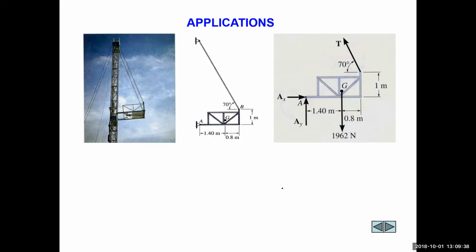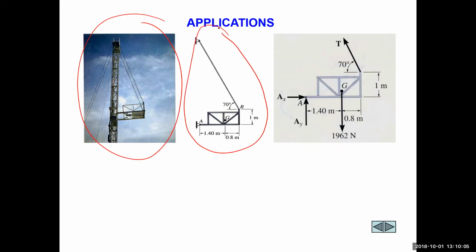So we're always going to look at just the external forces. So here's an application: a platform suspended from a tower. We might want to know what are the forces acting at the joints and in the cables. And typically what happens in real life, you're dealing with some real structure, and we then go through and idealize it. So we maybe look at it just in 2 dimensions if there's a lot of symmetry there. There's nothing different in the 3rd dimension.